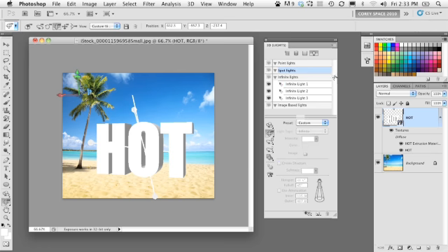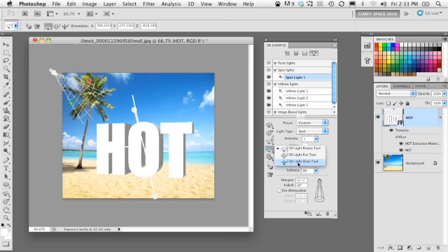So let's go into the lights section here. I'm going to go into the spotlights and go down here and choose New Spotlight. And there's the wireframe for that spotlight. It's pretty much in the right position, but we need to move it around. So let's grab the 3D light slide tool here inside the toolbar, and we'll click and drag. If you click and drag down, it'll actually slide the light towards you, basically coming at you in space.